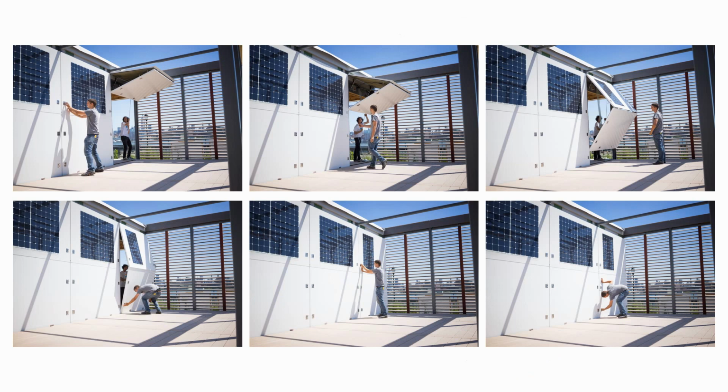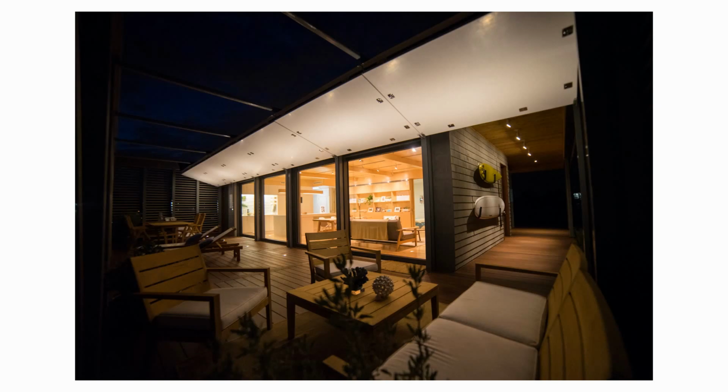We designed a simple 6-to-1 pulley system, a mechanical advantage pulley system, so that two people could easily close these and lock them down. The reason that guy's on the inside over there is because that's actually an outdoor porch. So this could happen in 10 minutes. You're closing these down, locking them up. And then, like I said, when they're open, they're really the most noticeable part of the architectural gesture. So just like the power system, they were integrated from the beginning.